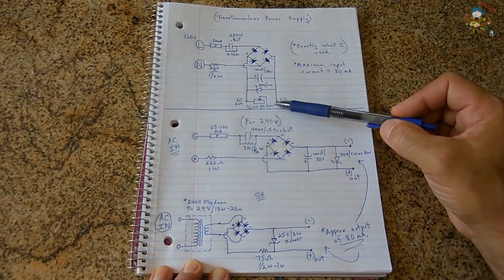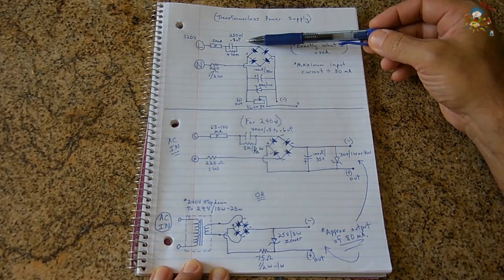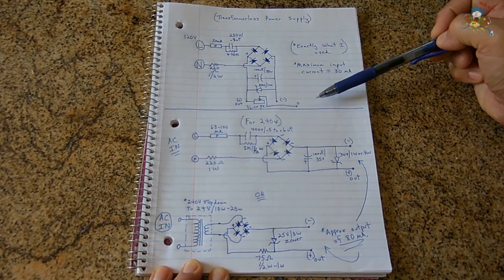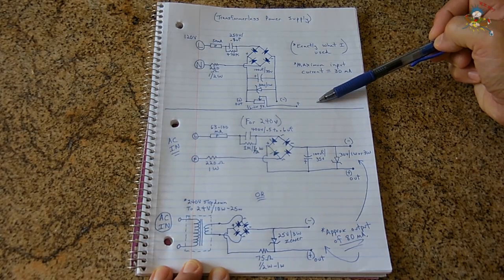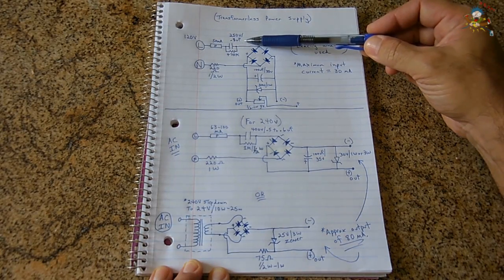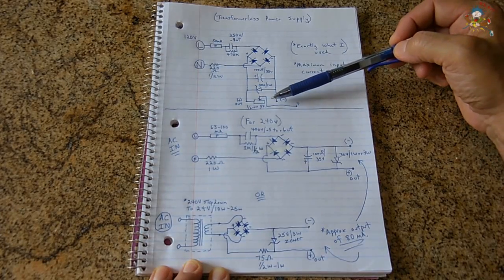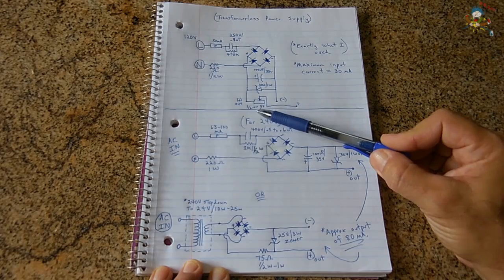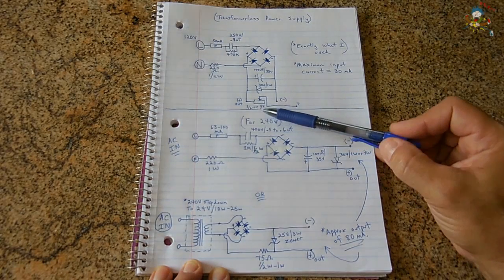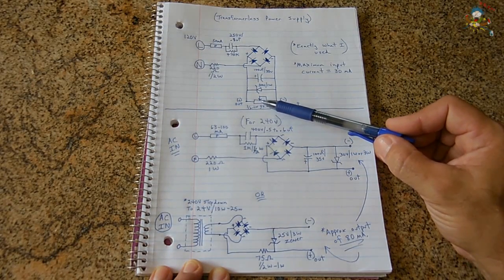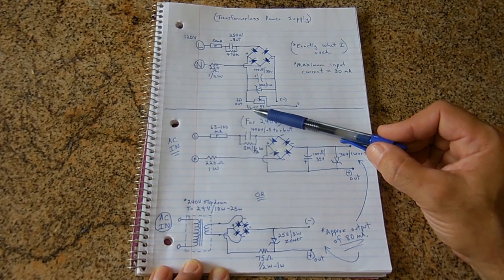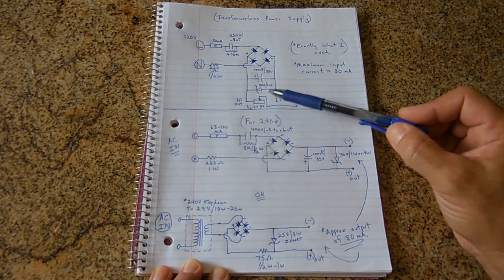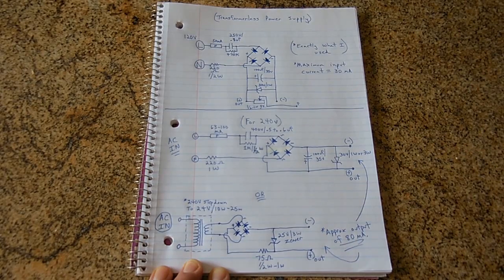The maximum output current using 0.8 microfarads is approximately 60 milliamps at 24 volts. If you raise this to the 1.1, then you'd be putting out closer to 80 milliamps, and you should still be fine. I would just try and go to the 1 watt if you have it, to make sure that this doesn't heat up at all. Now when I use this, I don't have any heating coming from this potentiometer, using it with the 0.8 microfarads, so I don't think you would have any issues if you did use the 1.1 microfarad value.